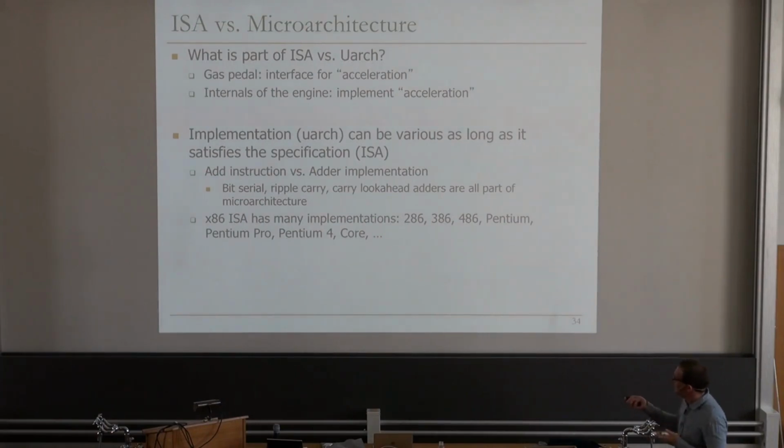Okay, I think ripple carry adder is another example. Basically, you don't do a single bit, but you do multiple bits. But what you do is your critical path is determined by how fast the carry propagation is, basically. You generate a carry, and the next bit computation can start only after you generate this carry, and the next bit computation can start only after you generate this carry, and so on. So it's slow, basically. But it's not as slow as a bit serial adder.